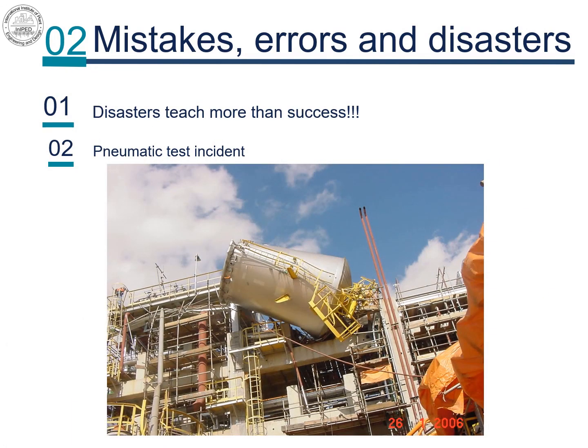Here can be seen from another angle the extent of damage. Note the unadulterated workout of energy that was stored for the test. Difficulties with pneumatic testing. Pneumatic tests are potentially more dangerous than hydrostatic tests because of the higher level of potential energy stored with compressed gas.